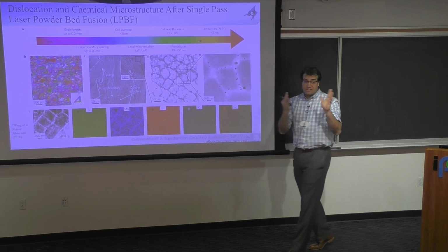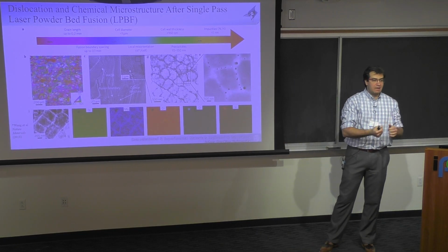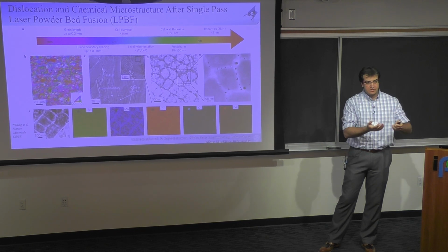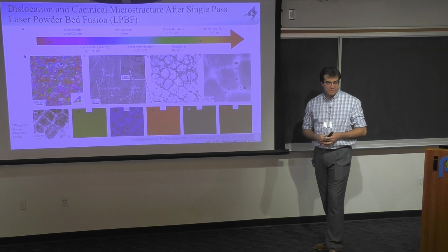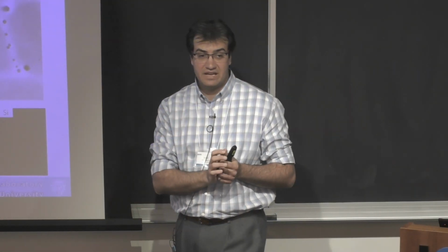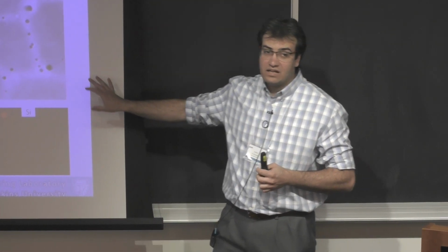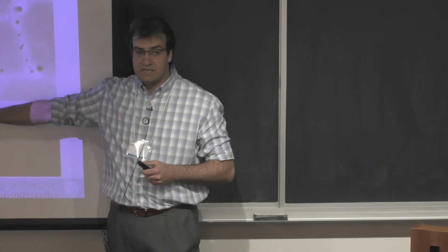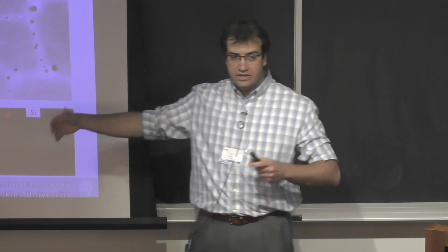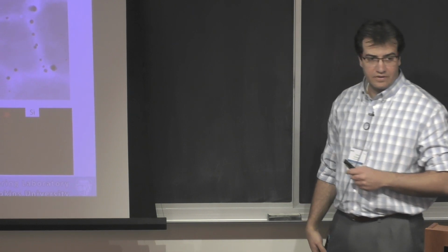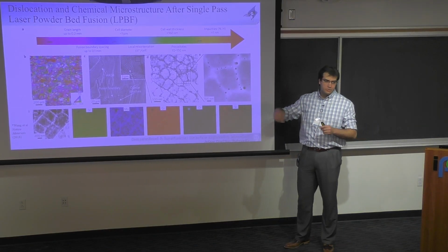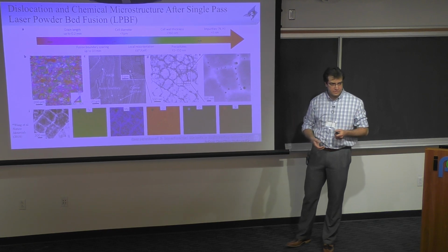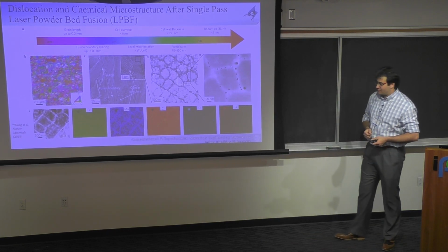Okay, but porosity is a completely important problem for additive manufacturing as well. This is another issue that affects fatigue life in additively manufactured samples. It all depends on the material system that you're looking at. With 316L, they have been able to create samples with very low porosity, as far as I understand, from these techniques. If you look at titanium, typically if you try to make titanium alloys, you get a lot of cracks, you get a lot of porosities, and so on and so forth. So it all depends on the material.